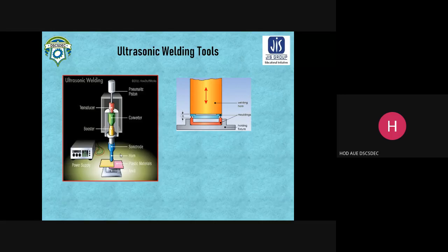Now, ultrasonic welding is also used to weld electronic components, and they are called semi-crystalline materials. In case of welding semi-crystalline materials, it would require much more energy. So obviously you need to select such a combination which will satisfy that. That means the horn amplitude and the booster amplification should be selected in this way. So everything depends on the workpiece which is to be welded. This is a basic idea, and you should have this.